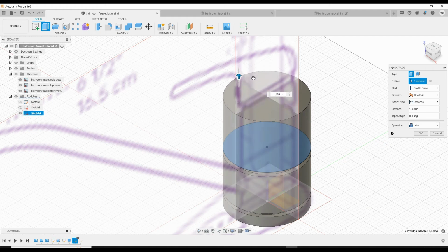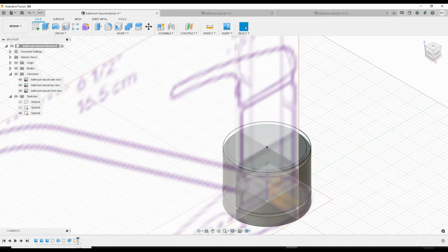Now, I did that fairly quickly, but I'm gonna show you guys what I did. Okay. So I did a multi-highlight. So I click on the surface we want to extrude. And since we created an outside diameter, the original diameter of 2 inches, we're going to hold down the shift key, left click that outer, and it's going to highlight both.